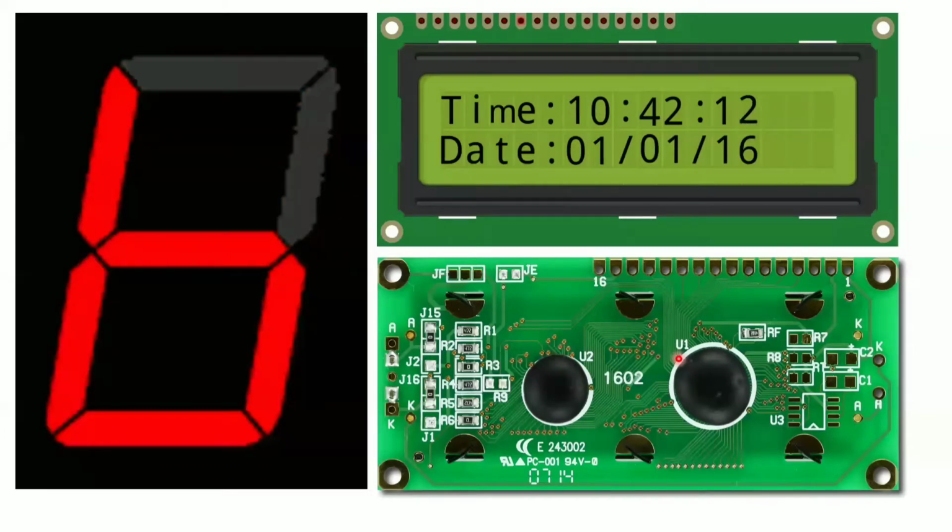Okay. Now why do we again require the 8051 microcontroller? So the 8051 microcontroller is required to send the commands to the display, and the 8051 microcontroller is also required to send the data to the display. Okay, first you will send the commands, later we will send the data. So depending upon the commands received by this liquid crystal display, the controller in it will be able to display the data which is sent by your 8051 microcontroller according to your command. Okay. So this is the need of the controller in this 16 by 2 LCD. Okay.